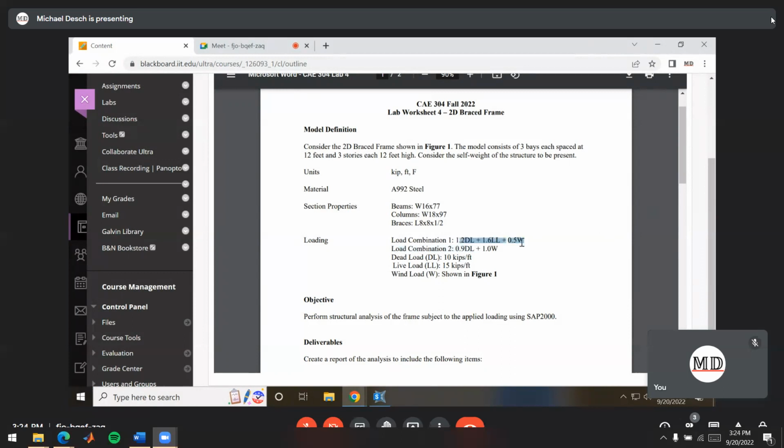We use load combinations like this. In ASCE 7, we have a whole bunch of these. There's like 5 normal ones and then some more for lateral loads. What we do is plug all of our loads into these equations and see which one gives us the highest load combination. Then we design to that combination.